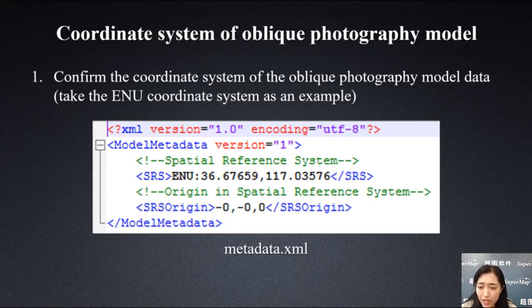generally used in construction engineering, and can also be used to understand the movement laws of other projects centered on the observer. So the station center coordinate system often involves coordinate system conversion during use. The ENU projection coordinate system function is used to project and transform the oblique photography data whose original coordinate system is the ENU coordinate system to the required target coordinate system.